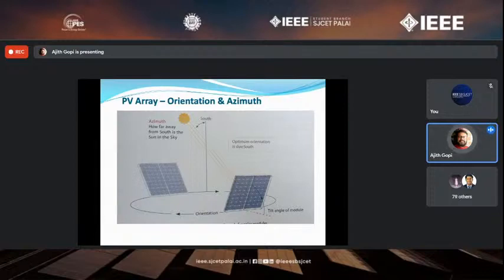So if I put my solar modules on the western side, and if I'm going to simulate in PVsyst or PVSol or any other software, I'll put the azimuth as -90, right? I'm not experimenting with any software here. I have taken a lot of sessions on software simulations. You can maybe listen to me on various occasions.